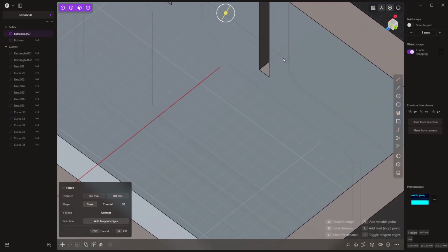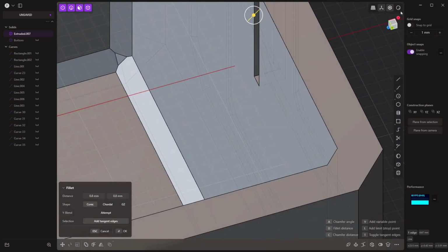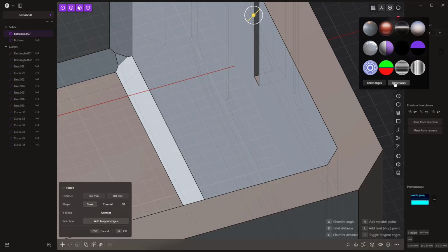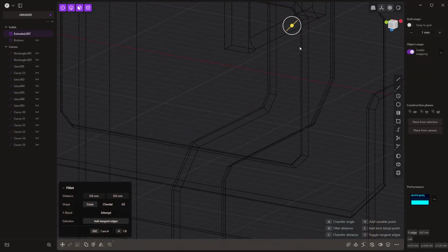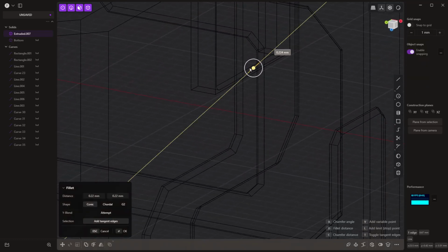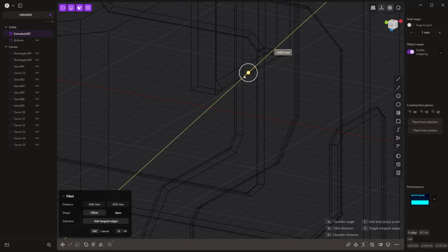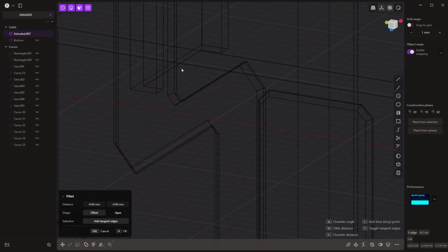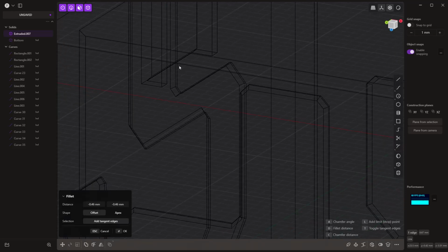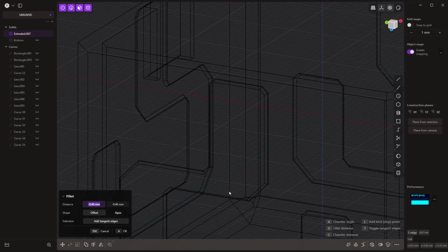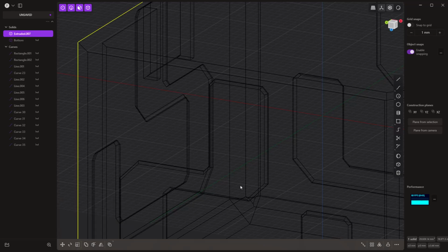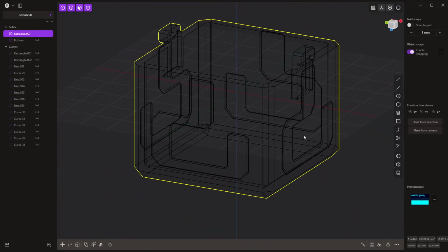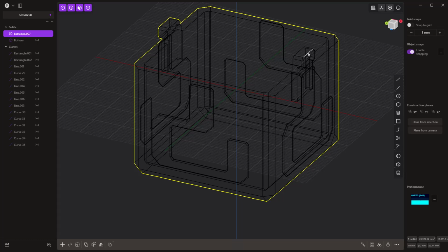There's not a whole lot of room there. It's kind of hard to see. If we turn off our faces, it might help see it a little bit. It really doesn't. So you may want to add a bevel here just to give it a little bit more strength. And we want to add that to both sides as well. So I'm going to come over here, hold down Control and grab this one. And I'm going to use minus 0.5 and minus 0.5. And basically all we're doing is we're trying to give that a little bit more strength because we are pushing